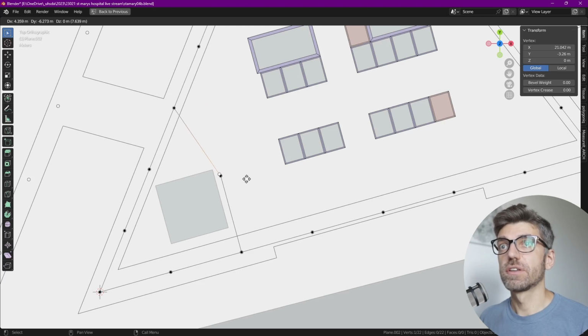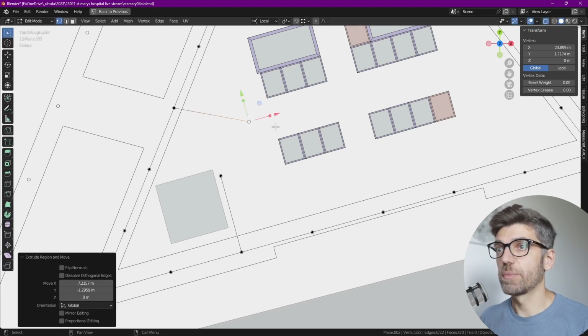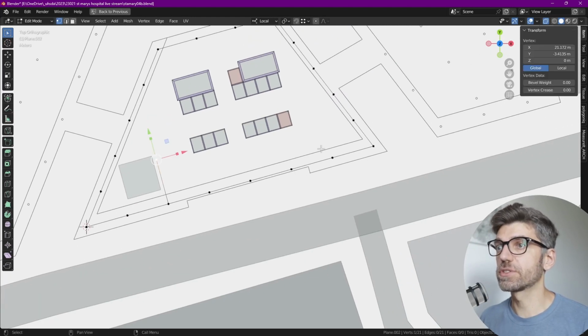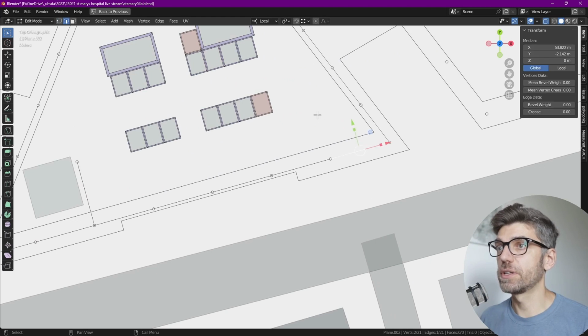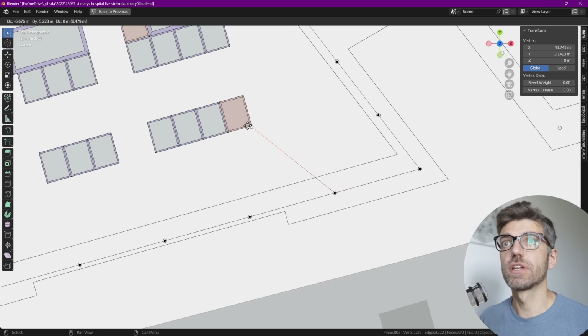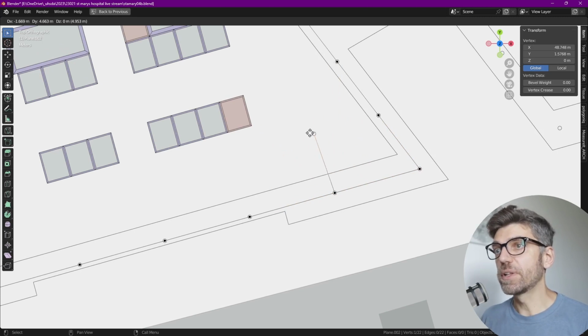So that's 7.5, 10 meters. So yeah, we have a bit of an extra length over here, but I think that's not too much, to be honest, not something to be worried about. So yeah, great. We can just get away with just one column in here. Now let's do a similar thing here. Let's do a sanity check just to see distances. So that's 8.5 meters. That's 6.5. And it would be great to have here, but I don't really think it's needed because even that distance there, that's a fairly decent span. It's not terribly big. Anything below 9 is okay.